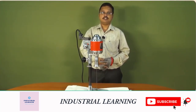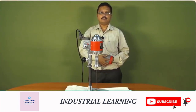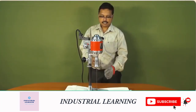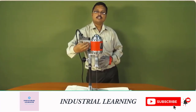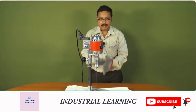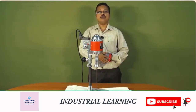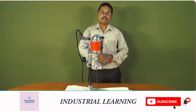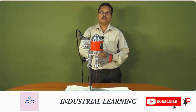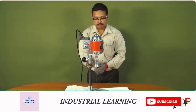This can be either achieved as marking in single plies using pens, chalks or using machines like this. This machine essentially has a needle which is a hot needle which is heated through this temperature control and it is plunged into the fabric lay and it leaves a hole where it touches the fabric, thus marking the spot. The depth of the hole is controlled by this knob and adjusting the distance between these two.